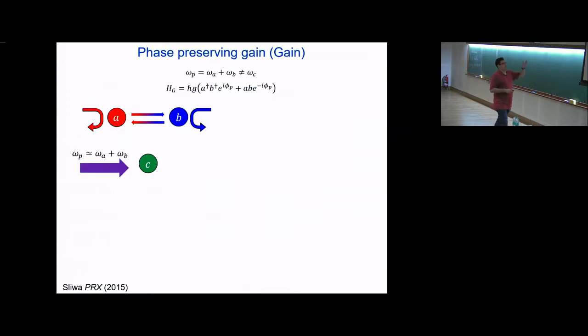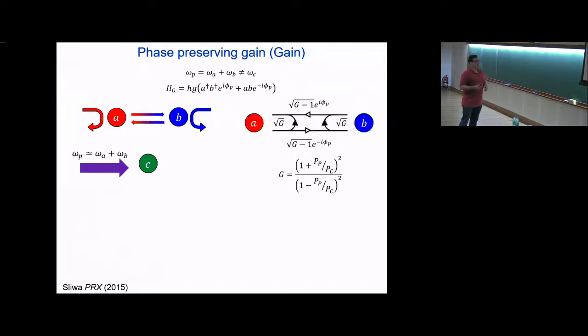Okay, so here's a schematic, again, of the system, getting a little more detailed. What we're going to tend to do in experiments is send some microwaves into mode A or mode B, or sometimes both. And again, now there's some coupling term we're going to discuss. These are going to be coupled at rates kappa A and kappa B to these 2 outputs. You should think of these as representing transmission lines or fibers, whatever your favorite way to route signals is.